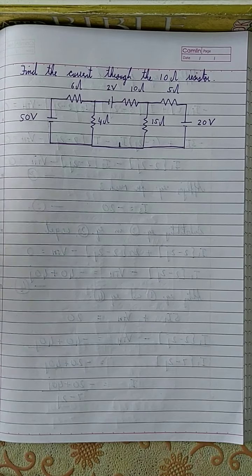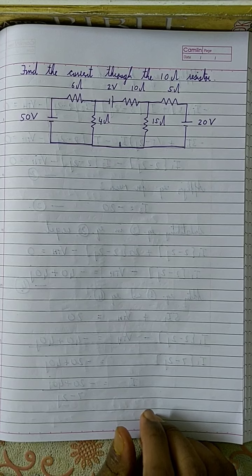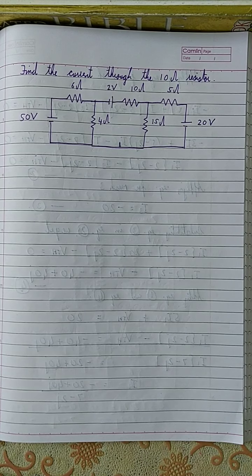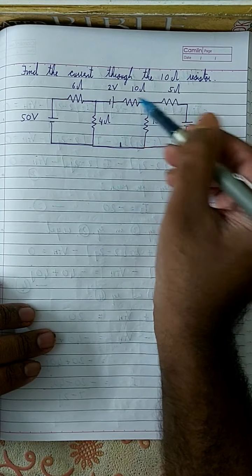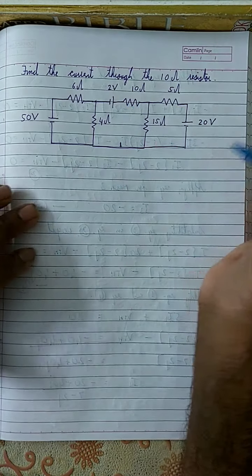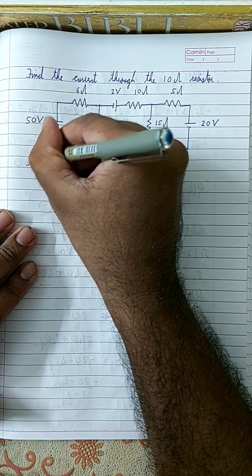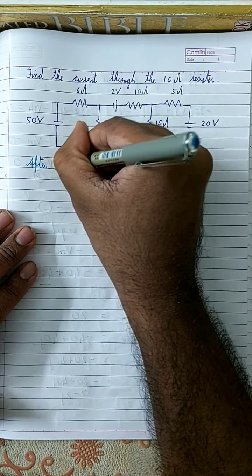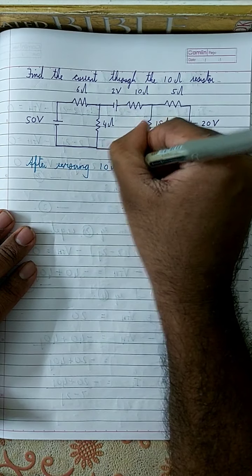So now let's do this question. Find the current through the 10 ohm resistor. Okay, so here this is the 10 ohm resistor, which means this is the load, which means this is what you're going to remove. So after removing the 10 ohm resistor,